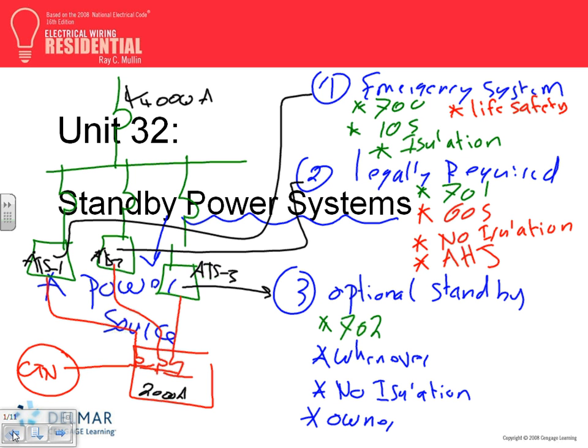When you lose the power, say you lose the 4,000 amp switchgear, completely dead, right? The first thing that happens is the auto transfer switch has some batteries on it that can sense that there's no power coming in. So what do they do? The auto transfer switch sends a signal to the generator to start the generator, because the generator will be dead. Now the generator is up and running. The generator is up and energizes this switchgear.